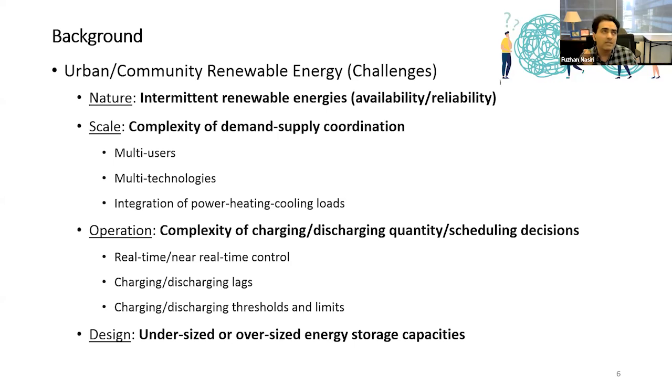So when we are making decisions to charge or discharge energy storage capabilities, that needs to be done with respect to something that is expected in real time and near real time or near future, because charging comes with a lag. It takes time for charging to take place, and it takes time for discharging to take place. So it cannot be at any instance of time, especially if the energy storage technology is of a mechanical nature, like thermal energy storage or compressed air energy storage.